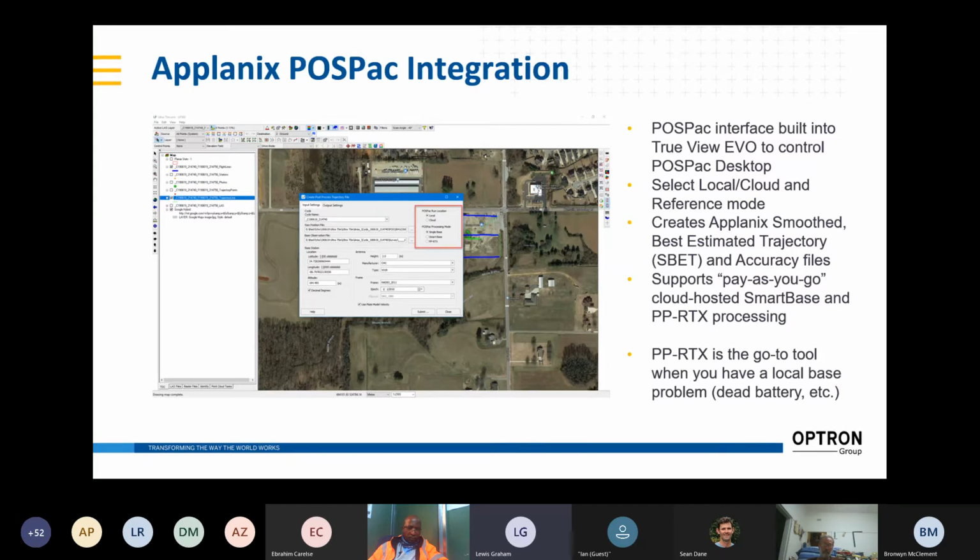Processing the position orientation data can be somewhat intimidating, because these position orientation systems are meant for many different kinds of vehicles and many different kinds of platforms. So you're often presented with a lot more options than you need to use to process TrueView data. So we've enveloped the post-processing software for the Atlantic system within the TrueView workflow itself. So there's just a couple of steps on a wizard that allow you to set parameters. Most of them are pulled from information that was provided when you imported the project. So that step is really easy.